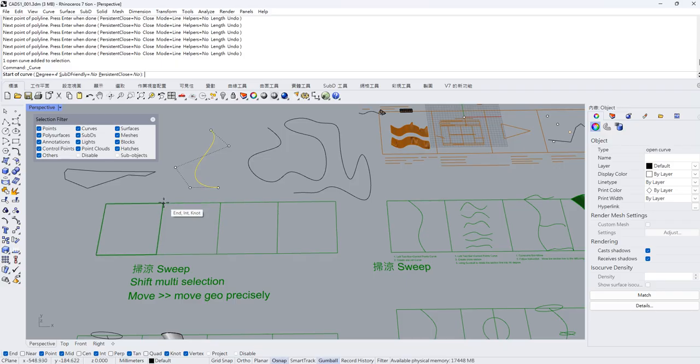It will help you move your selection or your point automatically to these reference points. So for example, if you want to snap to the midpoint of the operation frame, then it will show up middle. And here it will show up endpoint, intersection point, and knot. So basically, it's a supporting tool that can help us make our model much more precise. Okay, that means object snap.